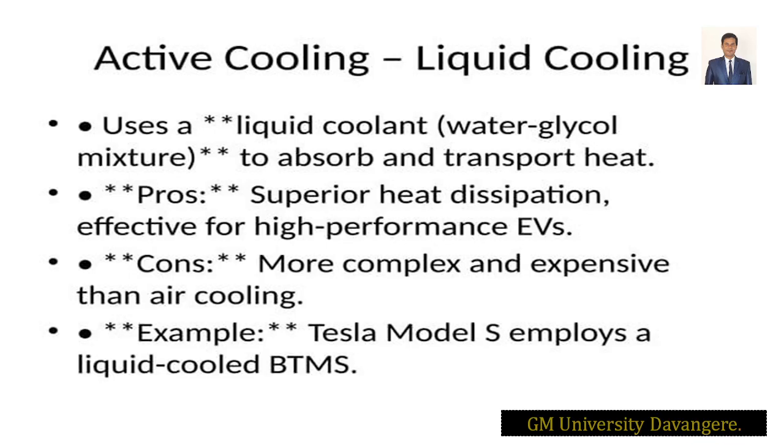So we have to think about the pros and cons of these types of liquid cooling, which is more superior and which has more complexity. The pros: there is more superior heat distribution, which is effective and increases the performance of electric vehicles. The cons: it is more complex and costlier than the air cooling system. For example, Tesla models have employed liquid cooling for the BTMS. Most cars, including Tesla cars, employ a liquid cooling BTMS system.